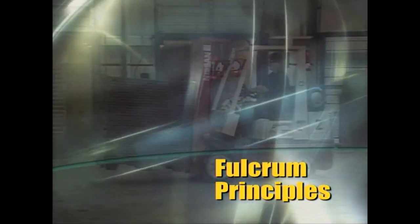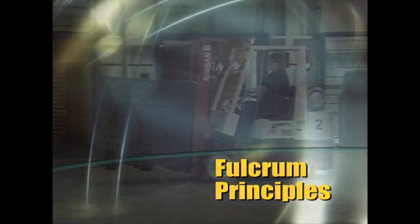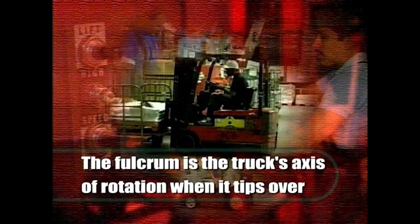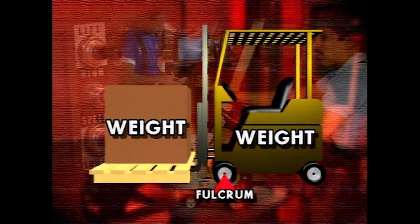Let's begin with the lever principle, specifically the fulcrum principle. Technically, the fulcrum is the truck's axis of rotation when it tips over. Simply stated, you have two weights balanced on a fulcrum like a playground seesaw. On the forklift, one weight is the heavy rear end or counterweight and the weight of the truck. The fulcrum point in this case is your front tires, and the other weight is the load you're carrying. The counterweight balances the load with the front tires as the fulcrum point.